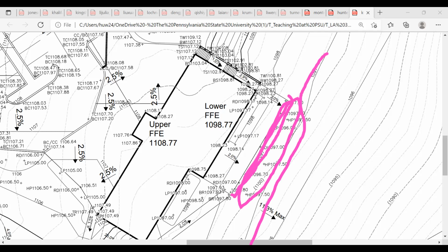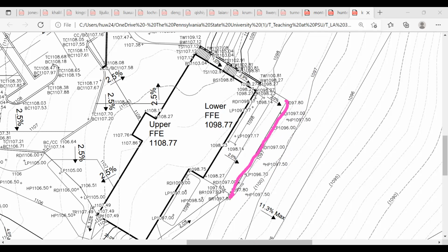That 1097 doing this indicates you have a very small retention cell at the edge of the plaza, and it feels like you're designing this pretty narrow on the edge of the plaza. We wouldn't necessarily design for a wall system here either, just because we have enough space, and building a vertical wall here is pretty expensive. Kind of makes sense?